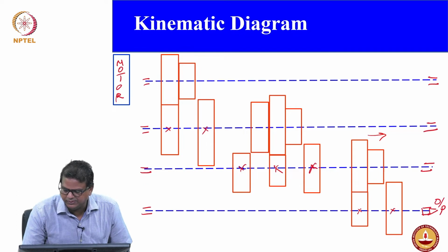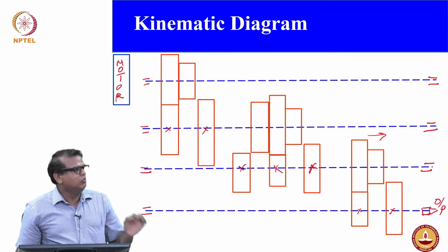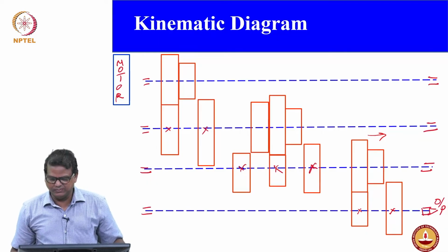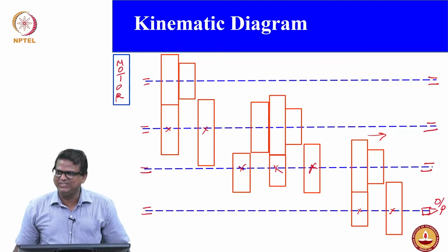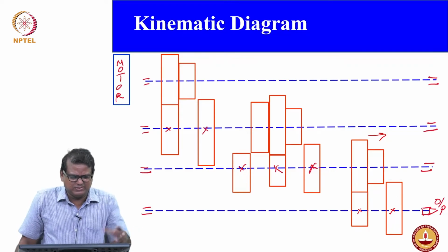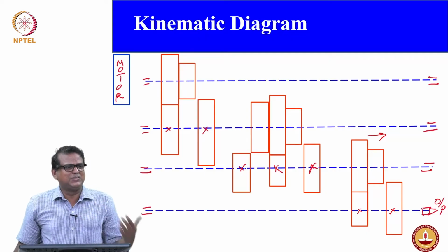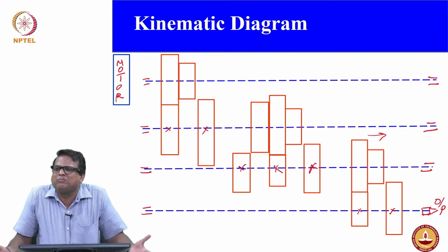Anything you mark with a cross indicates they are fixed gears, they are not movable, they are always fixed to the corresponding spindle. Okay. Fine. So now we have completed, okay. But still you can ask a question: we have constructed 2 gears in the first stage, 3 gears in the second stage and another 2 gears, but I don't understand how I achieve 31.5 RPM.